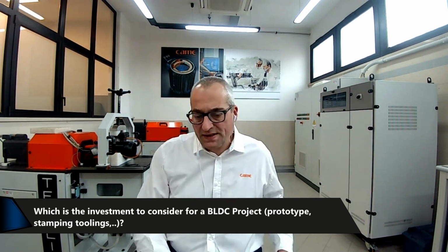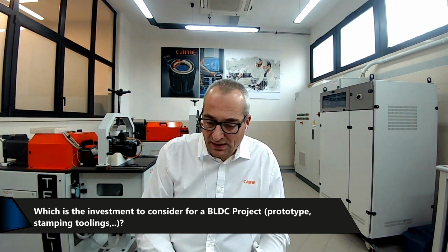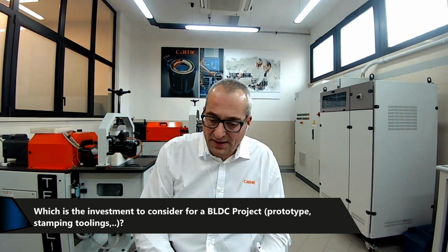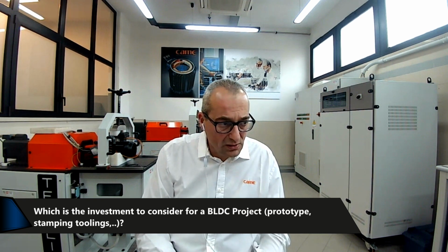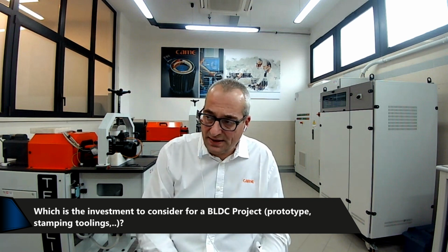The good approach is to start with some laser cut, because we don't have the tooling. There are no commercial parts, so you have to think about some laser cut samples. You also have to think about some 3D printing for the insulation cap of the stator. Because of that, we already jump into a cost of, say, between 1,000 and 2,000 euros, just to give a rough indication. Again, it depends on how critical the project is and all the specifics.